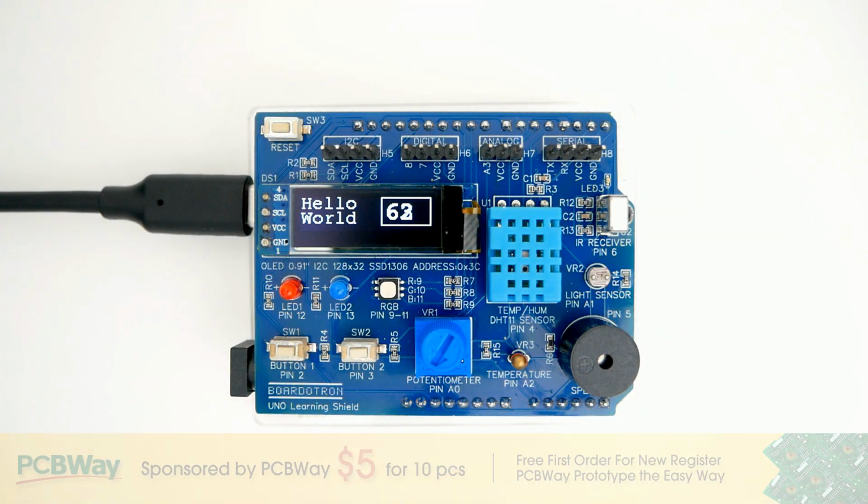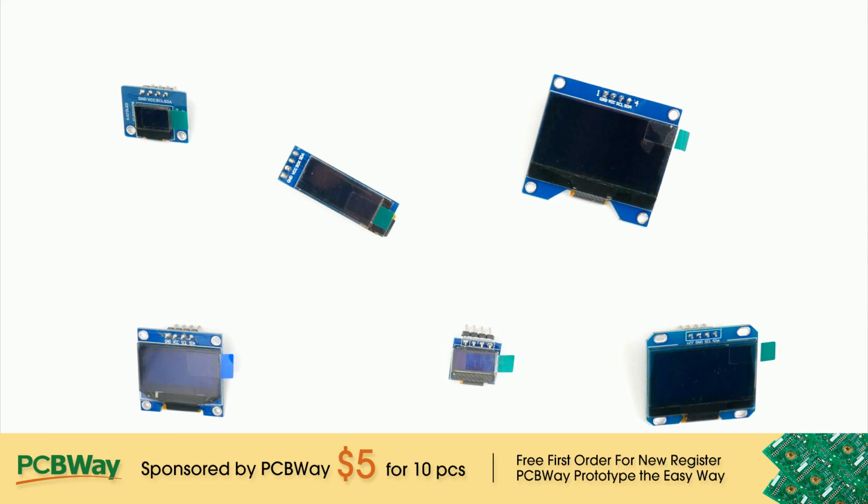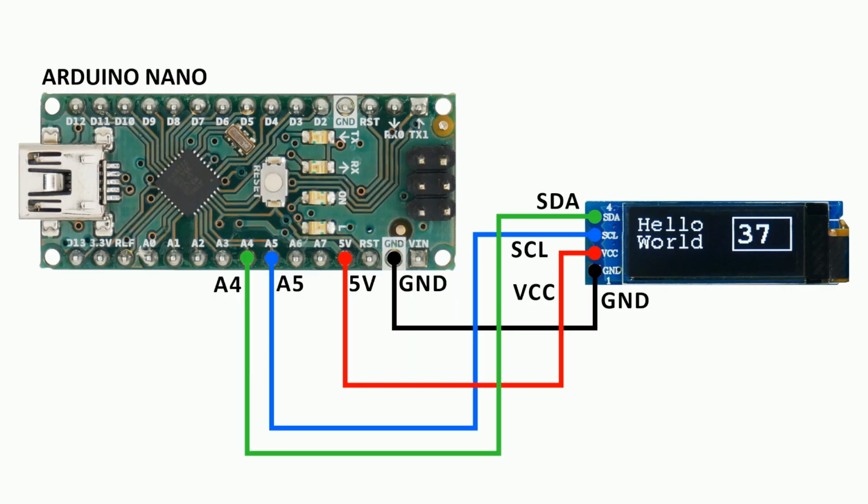Many projects require some kind of display, and one of the most popular displays is the OLED that uses I2C communication. It comes in several sizes and resolutions, but they all work basically the same way. I2C is a very popular protocol for communicating with external devices because it uses only 2 pins, and we can connect many devices using the same 2 pins.